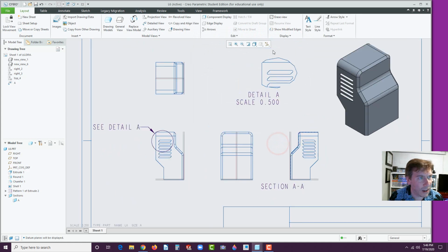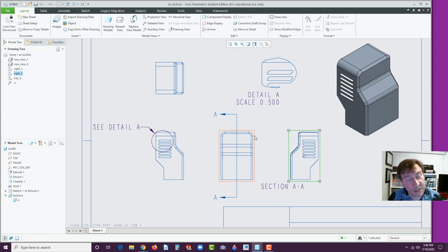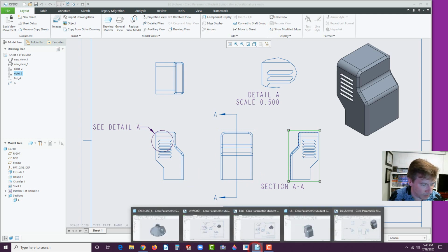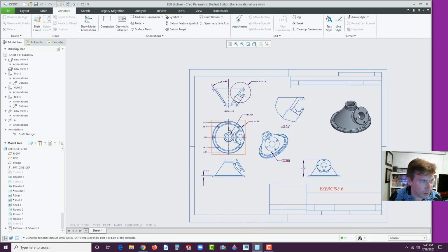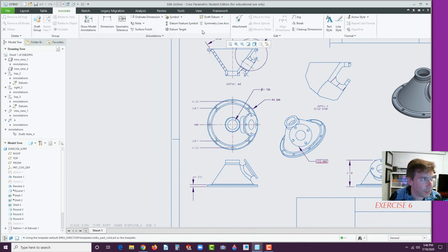Now here's how to get the arrows, but let's get rid of this plane first. Okay, now to get the arrows, select the view, go to arrows, and then click on the view it belongs in. So click here, arrows, and there. And so my apologies. Let's go back to that drawing really quick here to show you how that's done. So I needed a section right there.